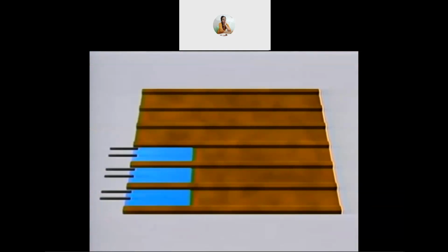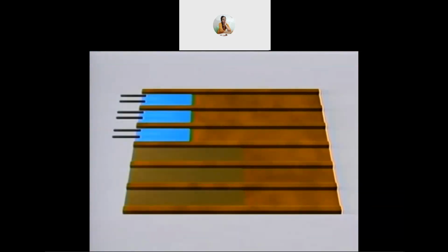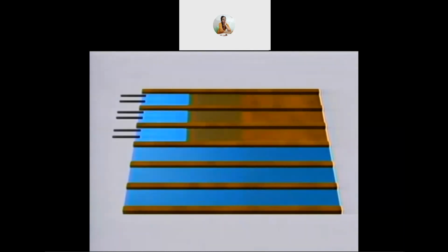With surge irrigation, you run the set until the water stops moving down the row. Then you move on to the next set. While you're irrigating the rest of the sets, the wet soil will seal, and when you return to your first set, the water will move easily over the sealed soil and onto the remainder of the row. It's almost like irrigating 2 short fields instead of 1 long one.